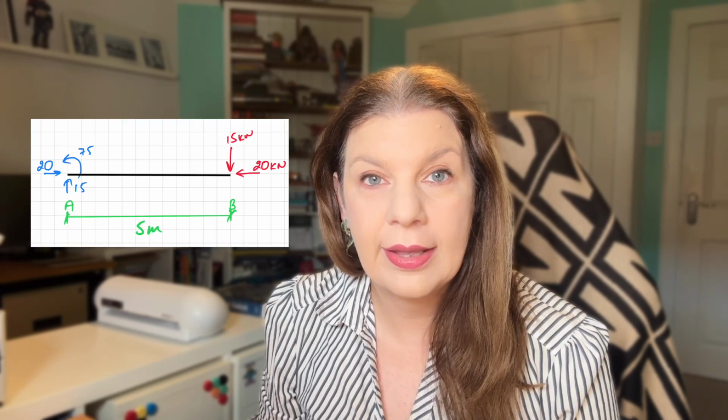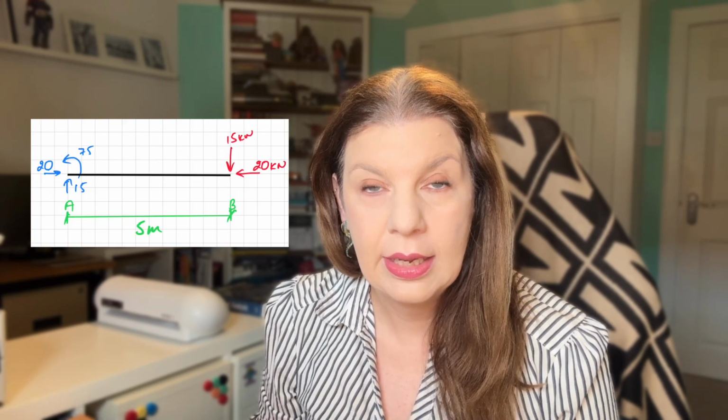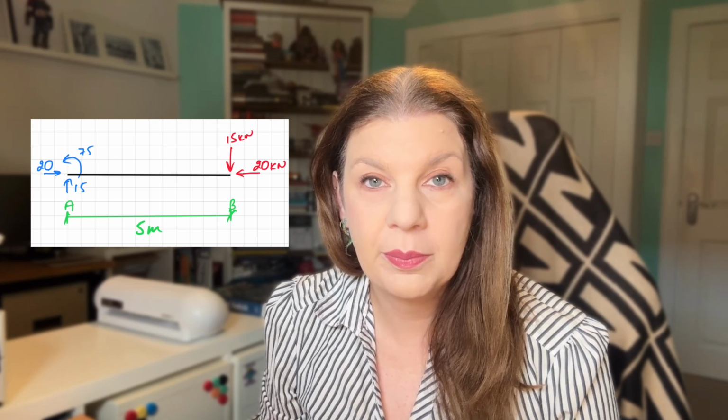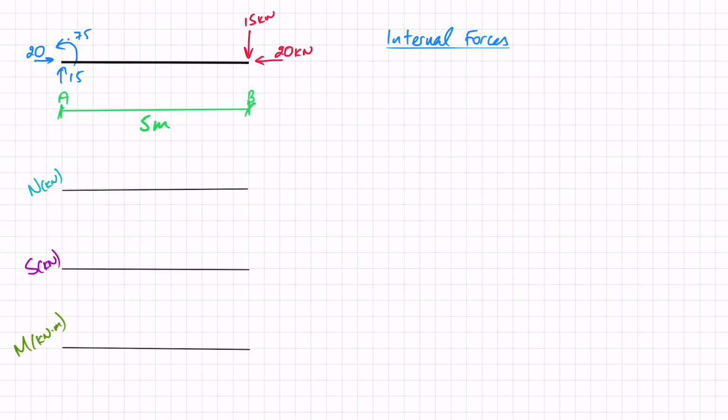And that's it. Now that I've got those reaction forces, and I've drawn that free body diagram, we're ready to find the internal forces. As we can see here, we've only got forces at that fixed end at point A and that angled force at point B. Nothing changes between A and B, so we'll only need one cut, meaning we'll solve this pretty fast. Let's do it.